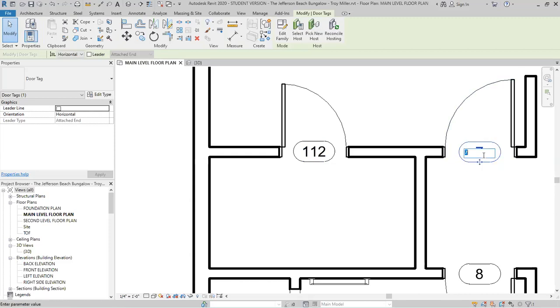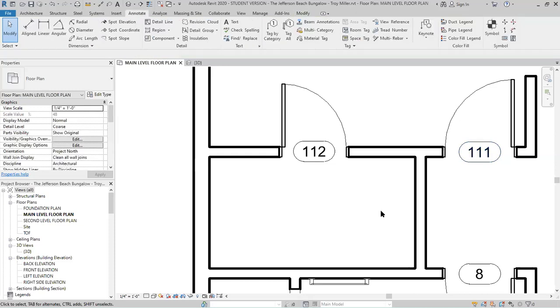One of the things I'll explain as I'm doing this is that, oftentimes with doors, and this would be more indicative of, let's say, a commercial building, the door number, let's say starting with 100, the first number of that sequence oftentimes will represent the level you're on. So if you had a 3-story building, then I would expect doors to be labeled 201, 202 if it was the second level, 301, 302 for the third level, and so on and so forth. So that's actually a very important thing in a building.